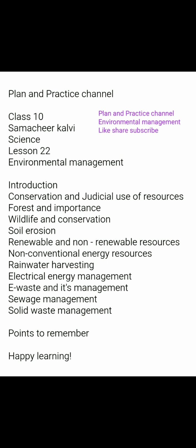Second one, sanitary landfill. Solid waste is dumped into low-lying areas. The areas are compacted by trucks to allow settlement. The waste materials get stabilized in about 2 to 12 months. The organic matter undergoes decomposition. Third one, incineration.